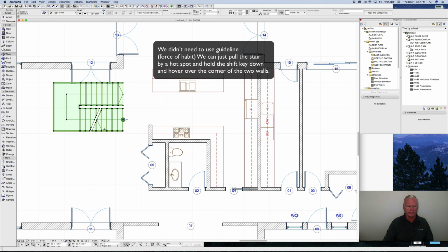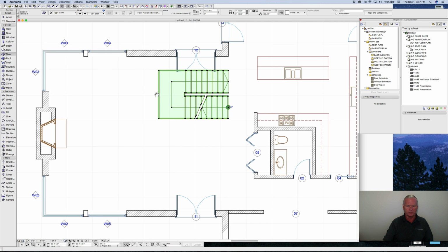And then we want to find a place that we'd like to put this in the center. Now unfortunately this doesn't have a center hotspot, so that we can't set it up for that. But what it does have is an edge on both sides. We have a bunch of hotspots there. So what we're going to do is go Control D, and we're going to drag this hotspot in the vertical position. Okay, we're holding down the Shift key, and we're going to come over here and find the center point of this fireplace. Now you're noting that I'm not getting a center tick mark.